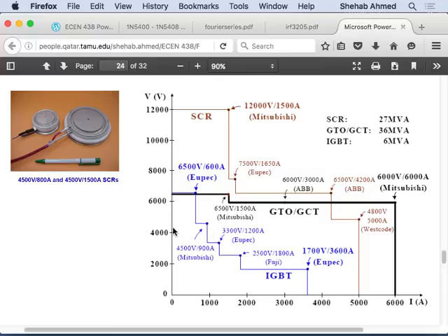In the example, we identified that I need a fully controlled switch. So I need a MOSFET, BJT, IGBT, whatever. I need something that I can turn on and turn off in a controlled fashion. Which device do you use? If you have an application with voltage and current characteristics here, 4,000 volts and 3,000 amps, I cannot use an IGBT. In that case, I can either use a GTO or an SCR, if the application is okay with applying the SCR, because the SCR looks like a diode in operating characteristics.